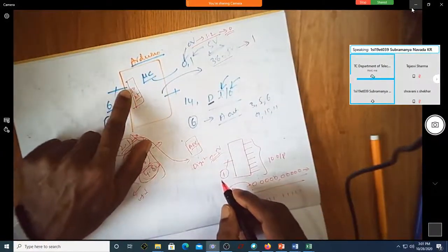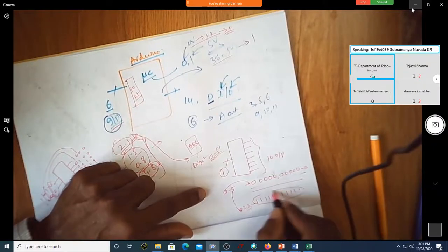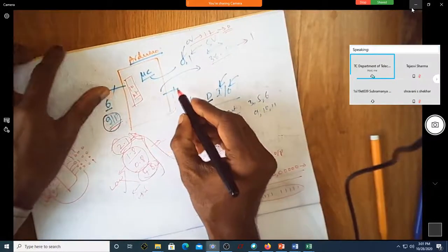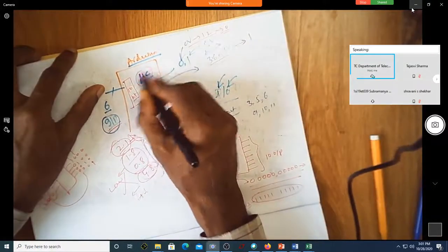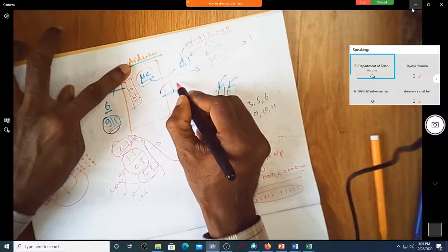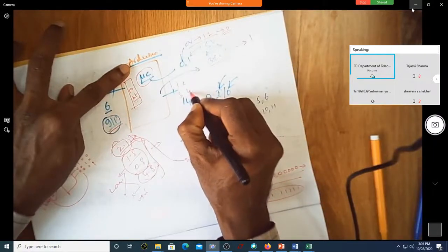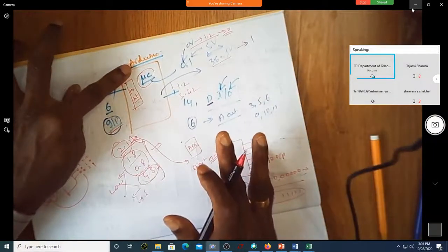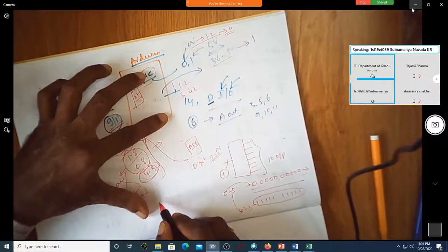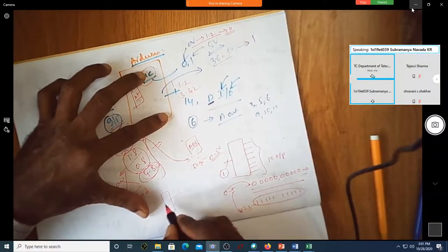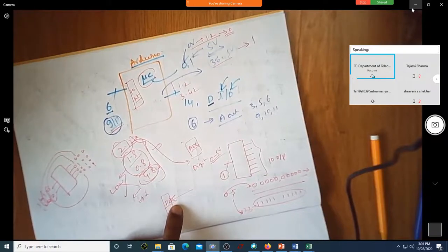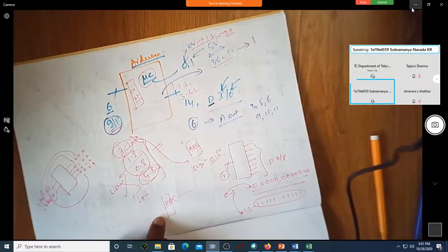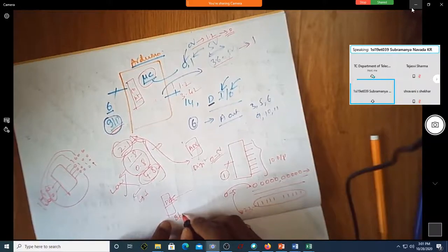So you are reading that inside, that will be 10 bit. Similarly, if you want to get an analog out, this microcontroller cannot give 1 volt, it cannot give 1.2 volt, it cannot give 3.42 volt. So what it will do is give the digital value, that needs to be converted through a DAC, a D to A converter, a digital to analog converter. This digital to analog converter is 8 bit.